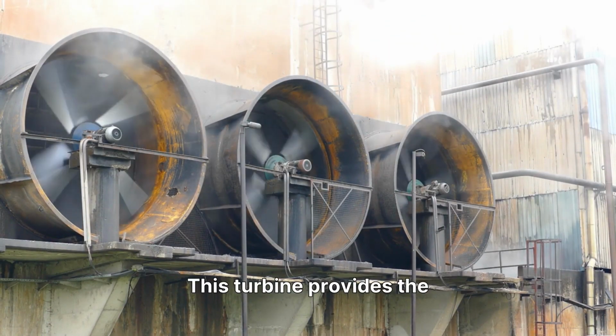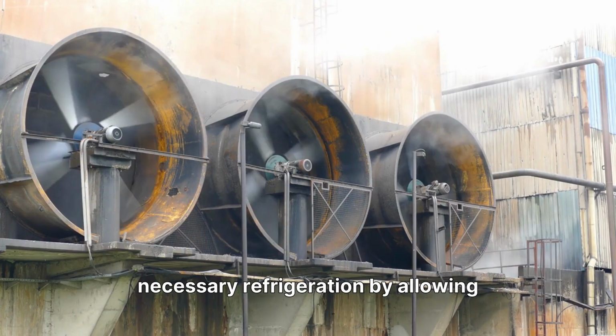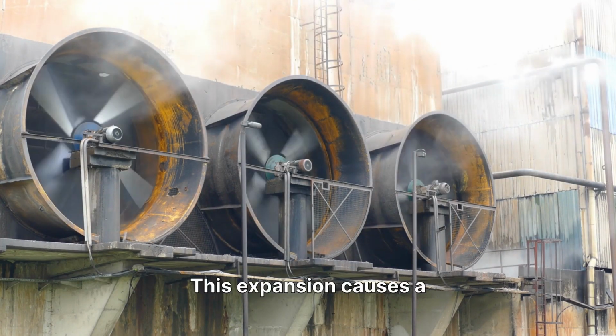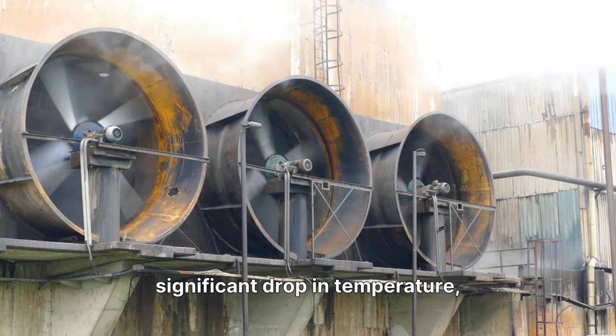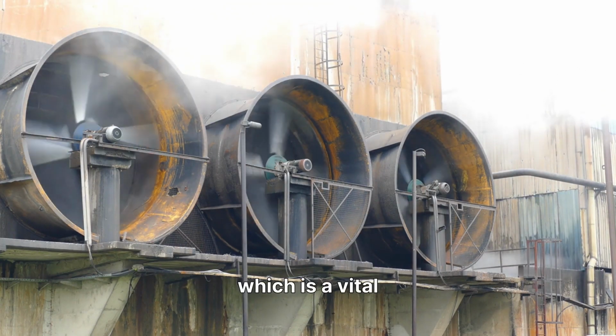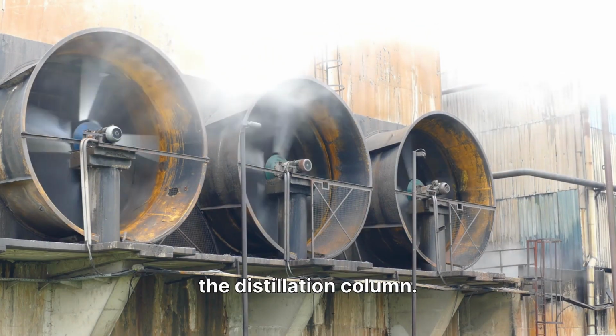A crucial component in achieving cryogenic temperatures is the expansion turbine. This turbine provides the necessary refrigeration by allowing a portion of the air to expand rapidly. This expansion causes a significant drop in temperature, leading to the partial condensation of the air, which is a vital step before it enters the distillation column.